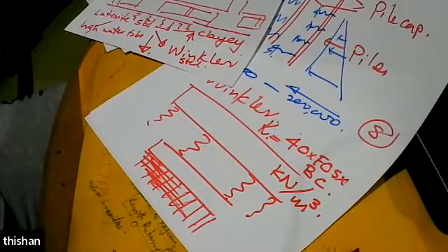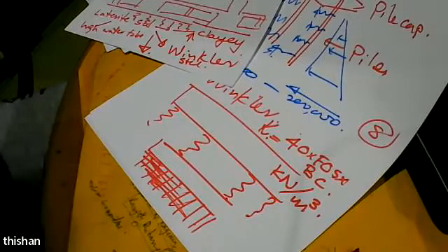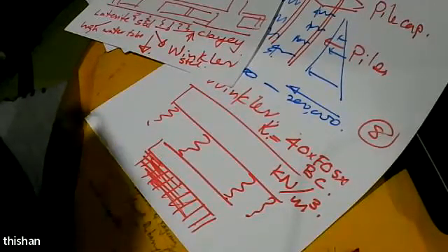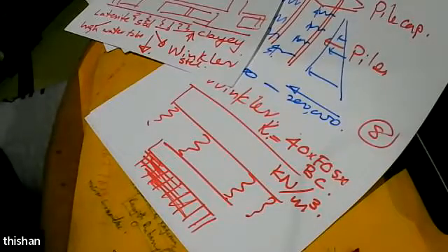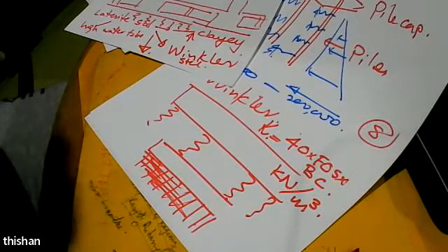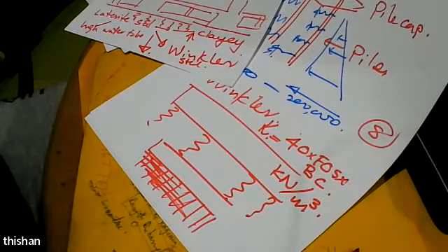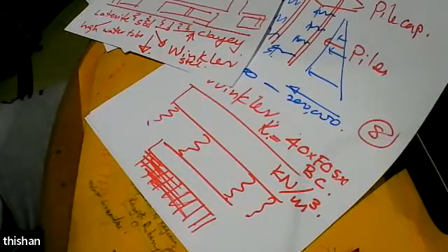Whenever you have extra components like rigid arms, you have used a special concrete which has no mass, no weight, because it's a fictitious member provided to assure the program the change in stiffness that can take place, or whatever the reason that you need the rigid arm.